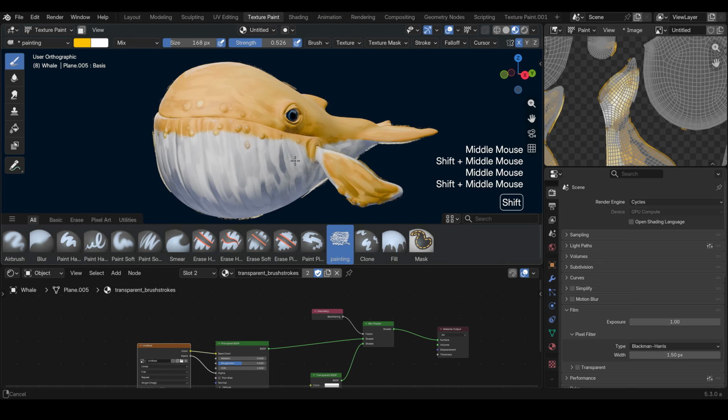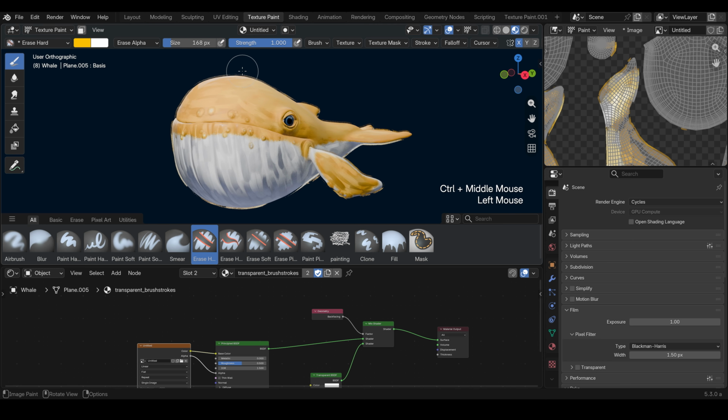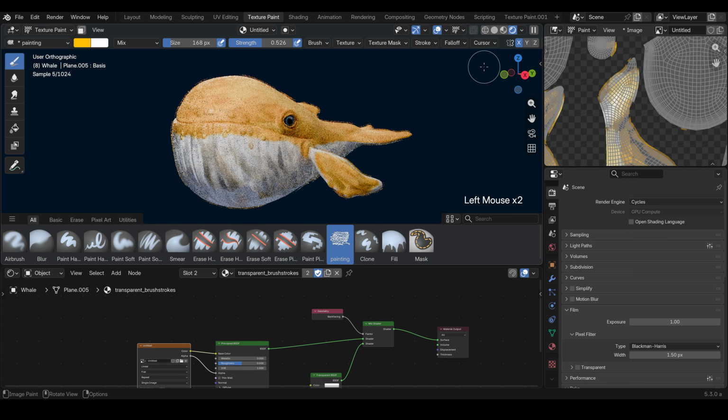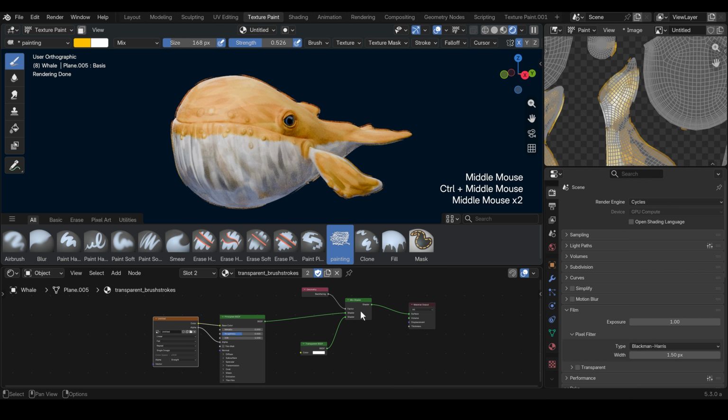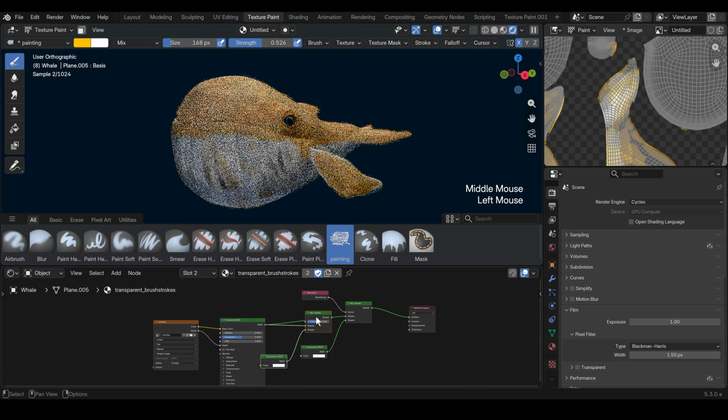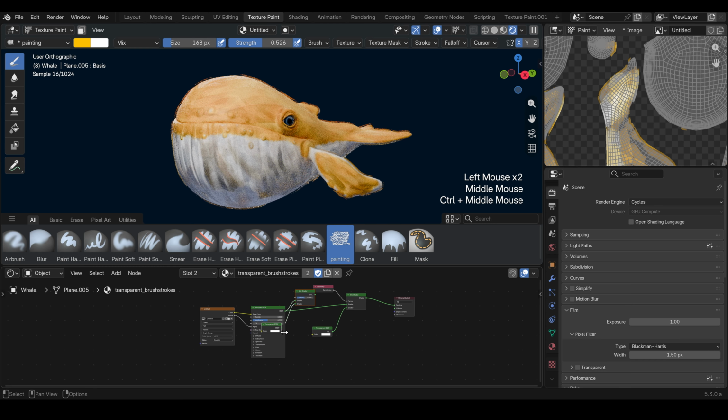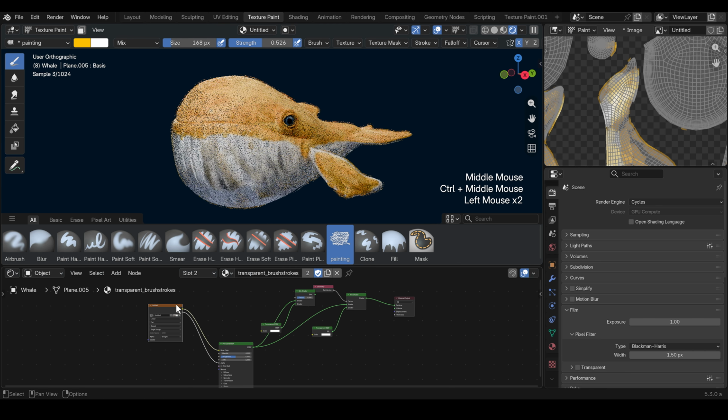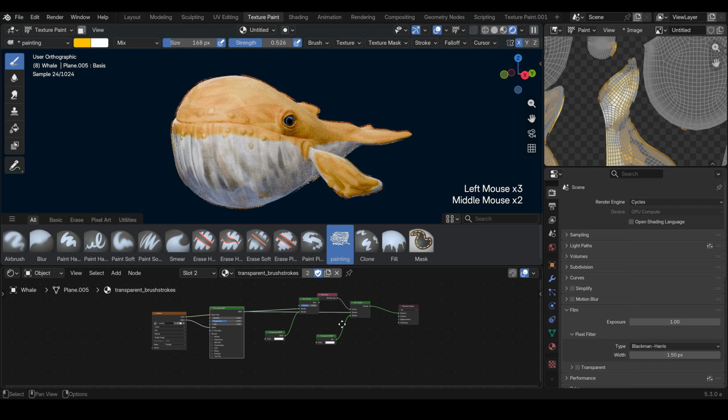And one more thing is that with our outliner at the moment, everything looks good inside the material preview, but if we go to the Cycles preview, we can see these strange shadows, and these are the shadows of our transparent material strokes. To fix that, we can duplicate the mix shader and the transparent shader with Shift D, then add this here, and inside the factor, let's maybe move the principled and this a bit to the back.